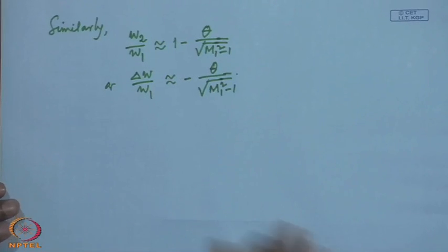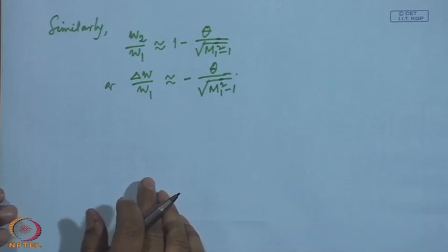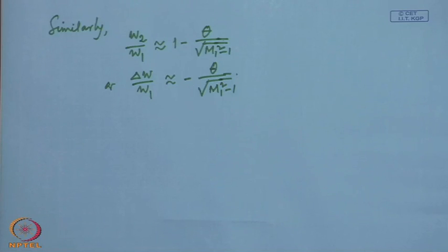Now, we will discuss the turning process or the supersonic compression using turning. We have seen that across a shock there is an increase in fluid pressure and density.